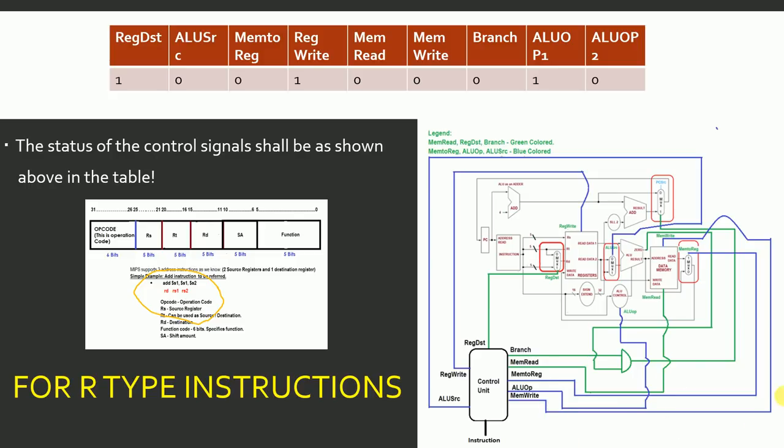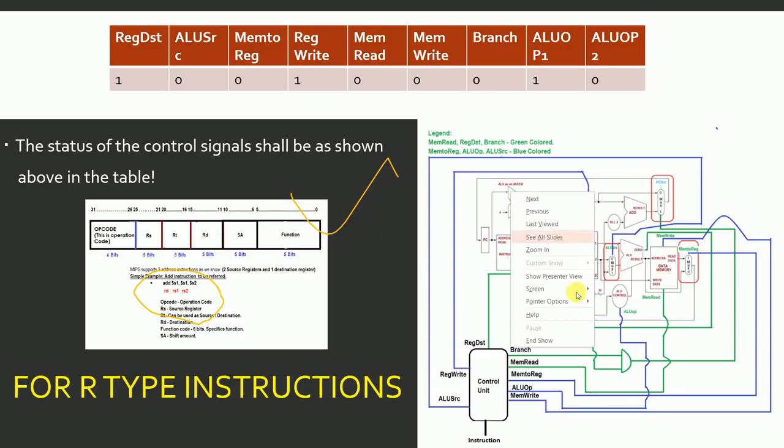Now see the status. I am going to use RS. So for sure, I will use RS here. I will use RT here. So RD comes here through this one and it is also in. So I need to also note RD. So REG-DST status will be 1. REG-DST is clearly high for R-type instruction. Now the first signal is cleared. REG-DST is high for R-type instruction.